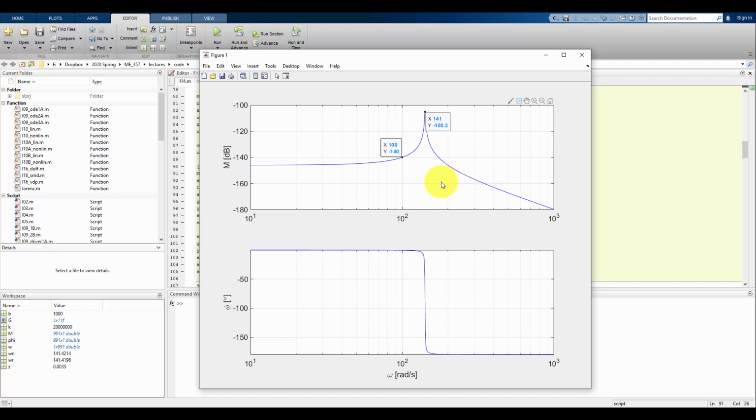So in this example, we were able to shift the peak of the Bode diagram to the right by modifying the parameters of the system itself, namely by doubling the spring constant. Now, that's again not always possible. We might not be able to modify the K, the B, the M of the machine. However, we might be able to. Another thing we could have done is increase the mass by adding more weights, which would also shift where this peak is, because we would be changing the natural frequency and thus the resonant frequency.